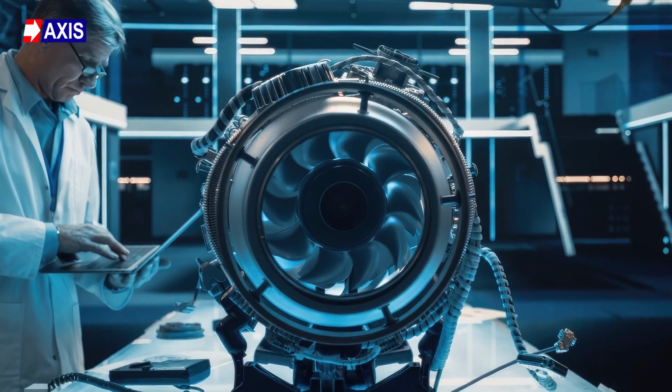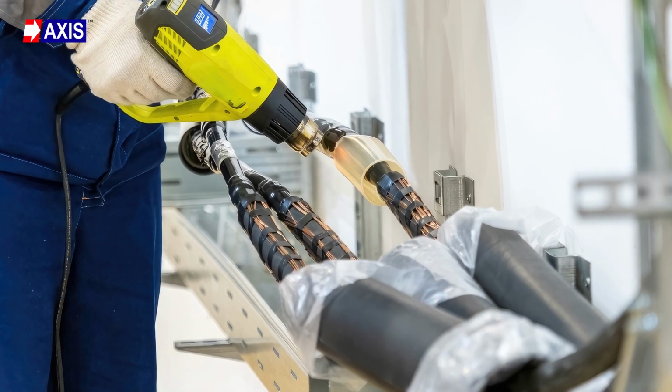For highly specialized needs, there are even higher ratios like 7:1 or 12:1. These are used in rare cases where the size difference between components is extreme or when covering damaged insulation. You will find these used in aerospace, defense, or custom repair work where standard tubing just won't do the job. Higher shrink ratios also make installation easier. They allow one tube to fit over large connectors and still shrink enough to grip smaller sections. This makes it easier to handle cables with uneven shapes or mixed sizes, and saves time.